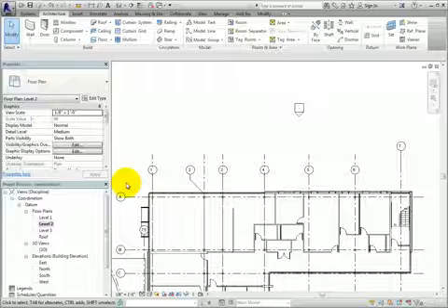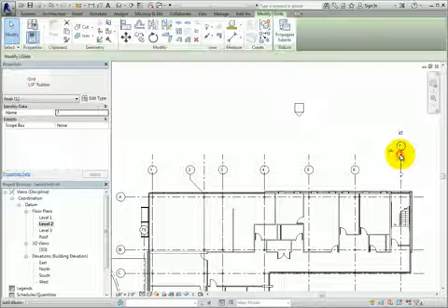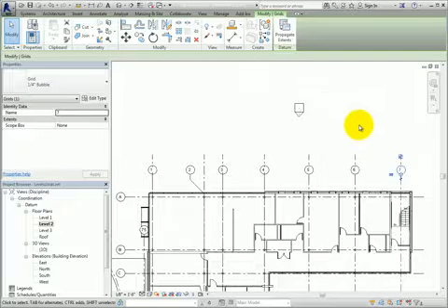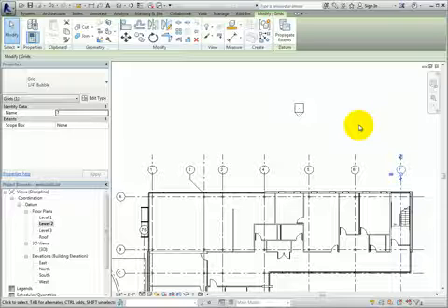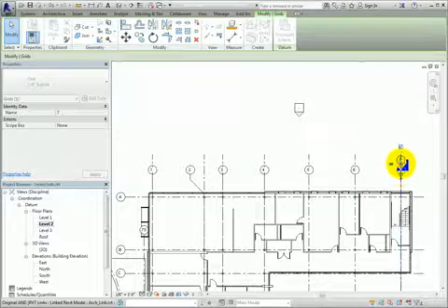If you want to undo your 2D changes, you can select the grid, right-click, and choose Reset to 3D Extents. This will extend the ends of the grid back to the 3D extent grips and remove any elbows in this view only.